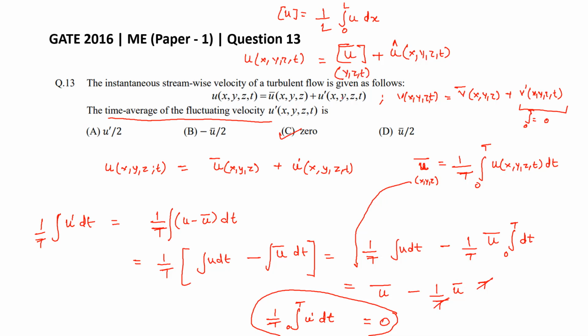So it's a matter of convention, but this will not be as useful as the time average, because here you have completely eliminated the time dimension. Here you still have some space dimensions. While solving Navier-Stokes, I don't know if you guys have heard of something called RANS. That is called the Reynolds averaged Navier-Stokes equation. There they will have a decomposition of U into a time-constant flow, sometimes called the background flow, plus the time fluctuating flow, which is that U prime.